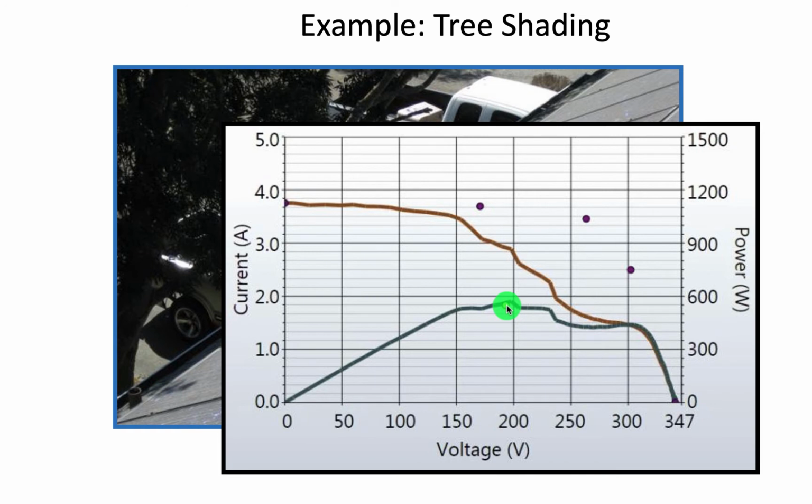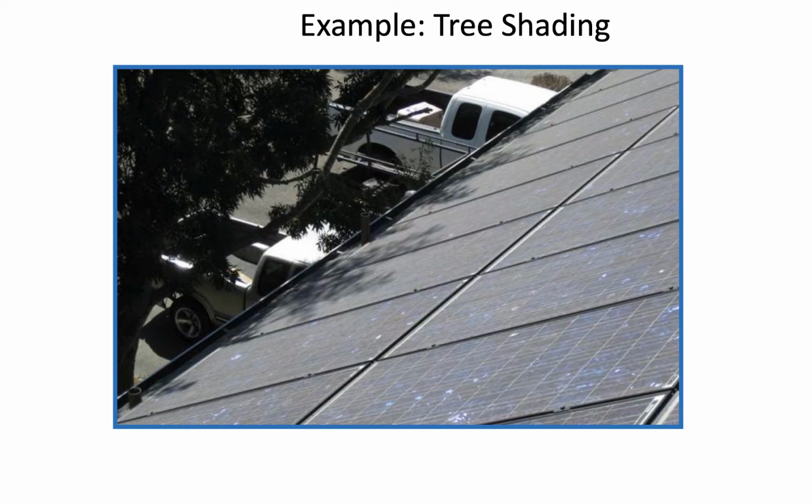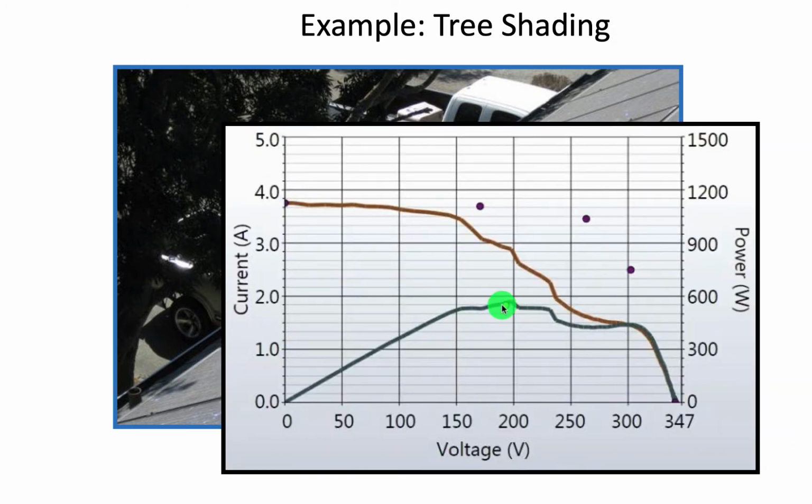So your maximum power point tracking inverter would keep the array working at about 190 volts for maximum power, which would be right here on the IV curve. Remember, I is for current, V is for voltage, IV curve. And here we have it superimposed on a power and voltage curve. So this shading in this situation with this string inverter is making about half the power that it could have made if it was operating at the maximum power point without shading.